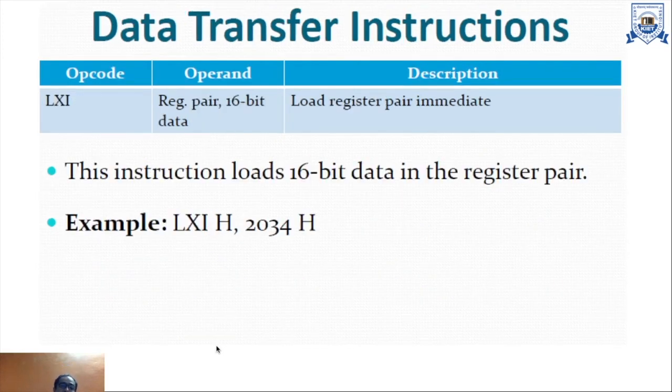And this is LXI. LXI loads the register pair, the HL pair, with the immediate address or 16-bit data. So what will happen in this is that it will load 16-bit data into the register pair HL.